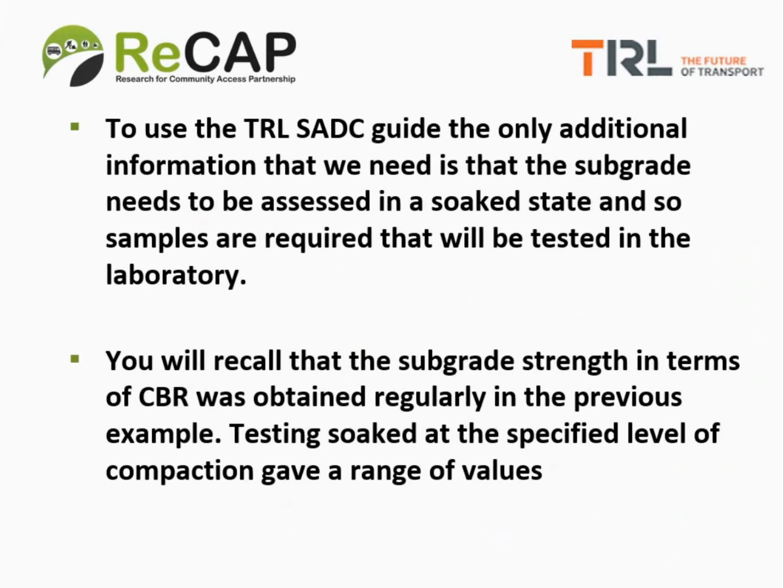To use the TRL SADC guide, the only additional information that we need is that the subgrade needs to be assessed in a soaked state, and so samples are required that will be tested in the laboratory at the appropriate density and soaked. That is not to say that we believe that the subgrade will be soaked in practice. We're soaking the subgrade simply to classify the subgrade quality that we have for that particular road.